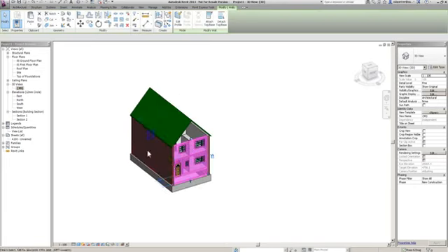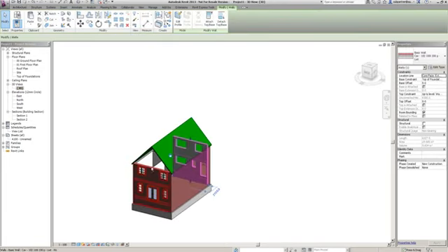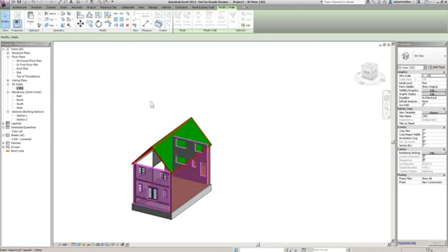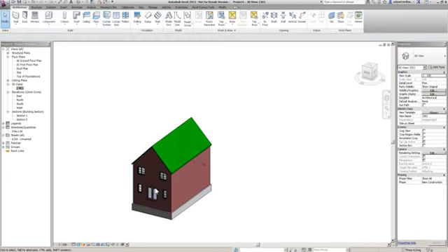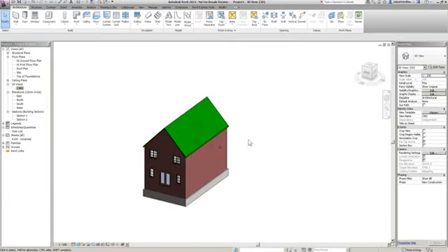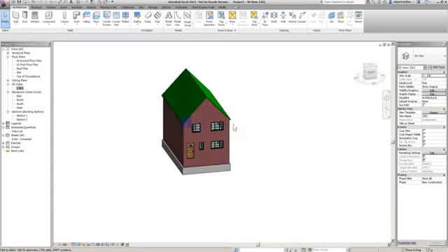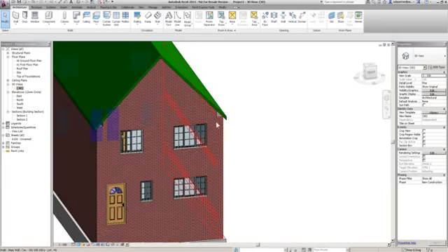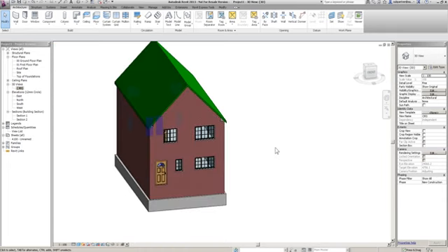Okay, I'm going to take that wall just there, flip it around, holding control, select that wall, and go attach top base up to this roof just there. Done. Okay, we have these little problems just here. We'll come to those a little bit later on. You see just there we've got these little triangular notches. It's just the way that the walls are cleaning up. We can change the order of how they're cleaned up a little bit later on. Okay, but for now that's it.